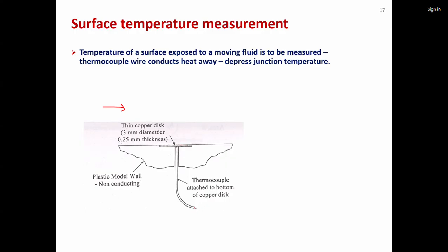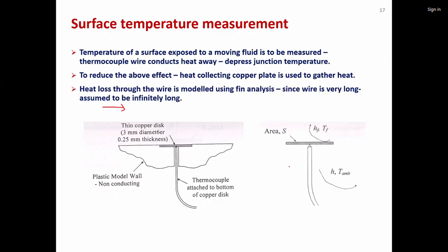Essentially, the thermocouple tip is mounted onto the bottom surface of this copper disc, and the other side of the copper is exposed to the process fluid. So the heat goes from the process fluid into the spreader, then to the tip, then to the wires. This is what happens in the thermal model.